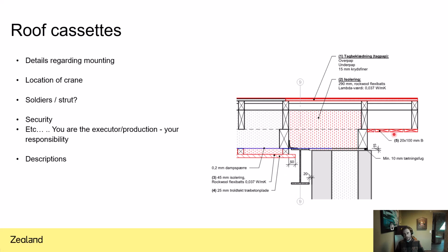Also, if we have any wood boards overhang, then you should have that in mind as well. If we need to put in some kind of insulation afterwards, and this one needs to be open for us to fasten it to the glue laminated frames, please have that in mind as well when you are making this.